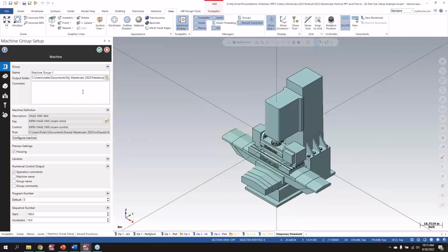So that's not in the software quite yet, but what this is doing is laying that groundwork so that if I do take the time to set up all my fixturing and all that stuff, the software, when I go in to do a specific toolpath, it'll know, okay, this is not machining geometry, I want to avoid it. So the end goal here is to get to where my retract heights are automatically assigned, I'm automatically avoiding clamps, work holding, anything like that. So that's just my little backstory on why this is different going into 2023.